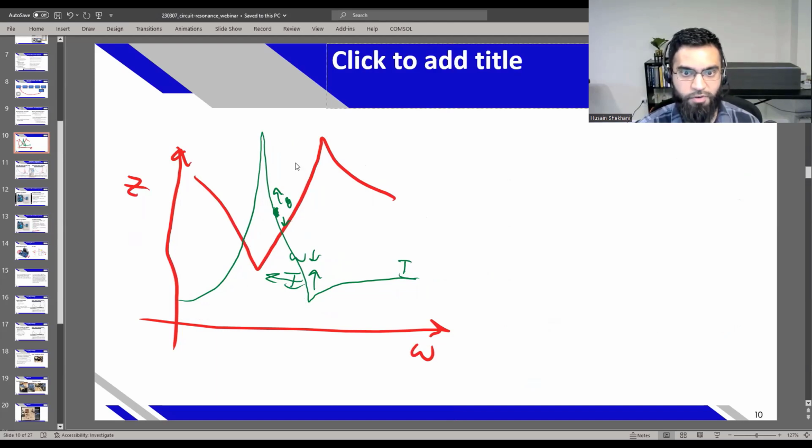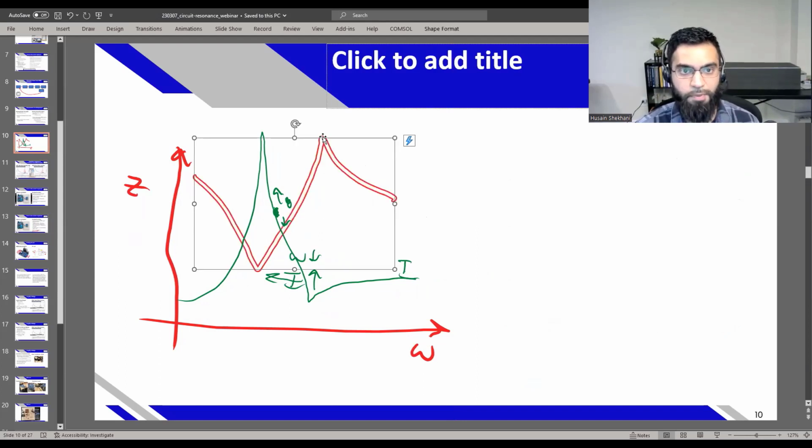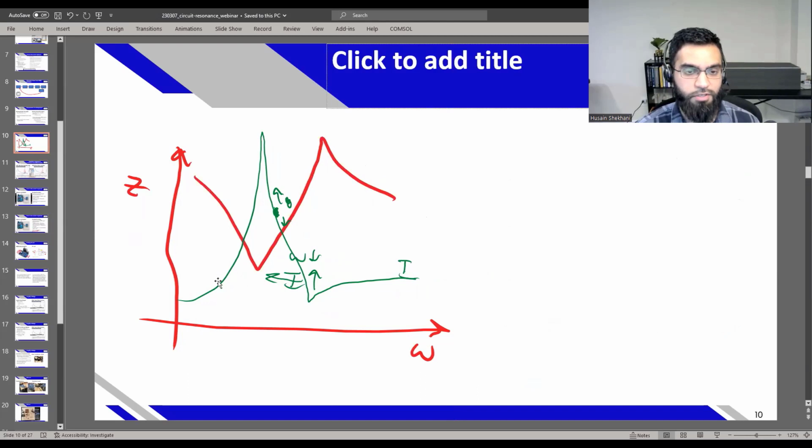The transducer does have a variety of characteristics you technically can choose from. You can also choose the high impedance point and drive at anti-resonance if you choose. You'll need a lot more voltage. So usually we like to drive at resonance because circuits are just easier to play with. They like more current. Many transducer designs go with more current. There are also other considerations. But resonance is more unstable than anti-resonance in terms of drive conditions.